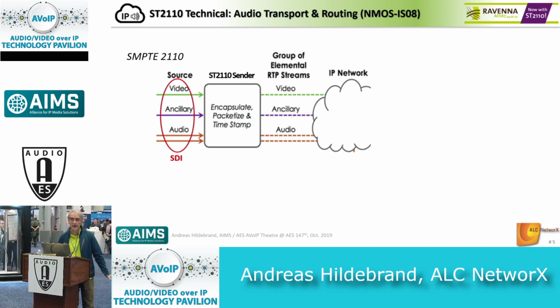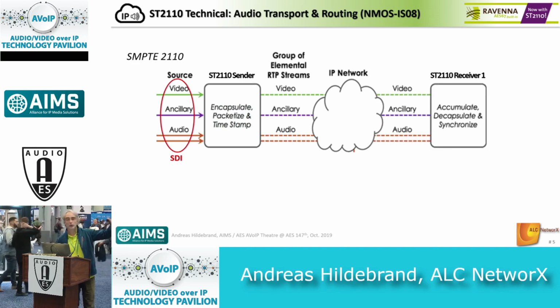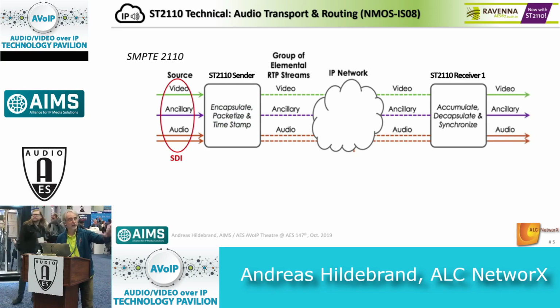They can be received anywhere in the network, and of course, if I want to rebuild the SDI signal, a 2110 receiver could subscribe to the video and ancillary data and audio data streams and can exactly rebuild, recompile the input SDI signal. Well, that would be of no particular use. We could use 2022-6 for that.